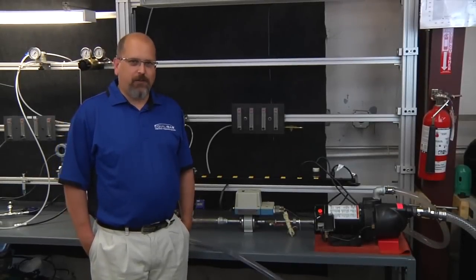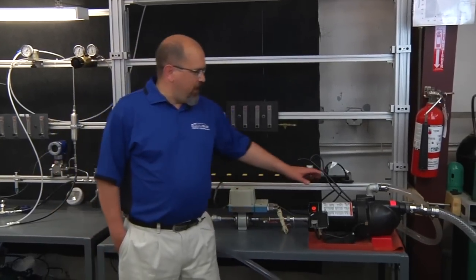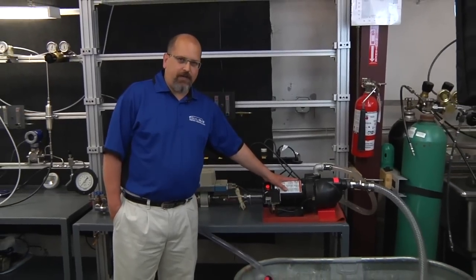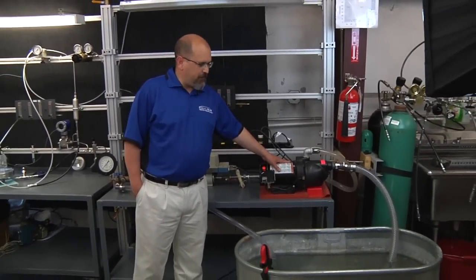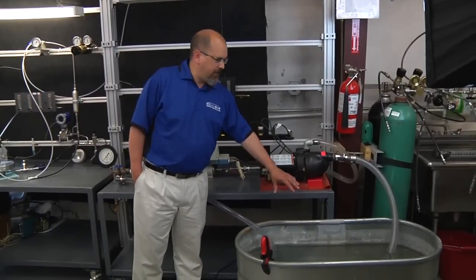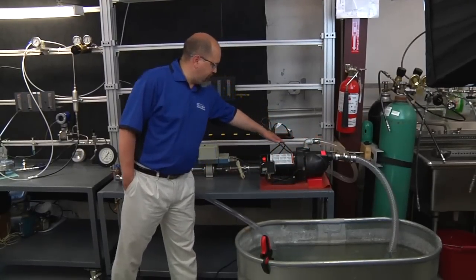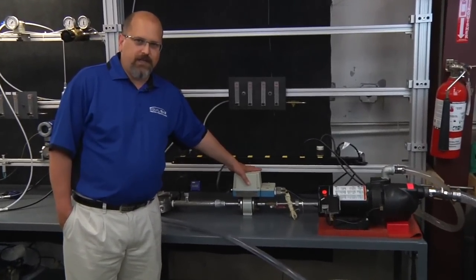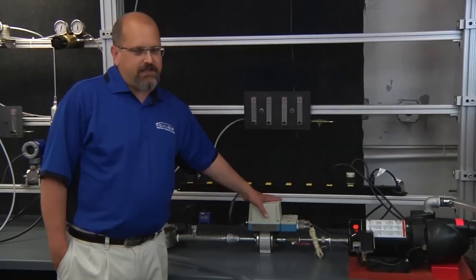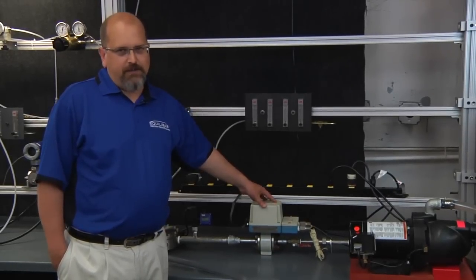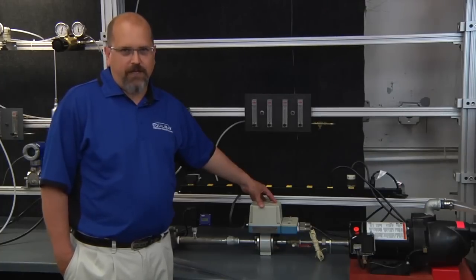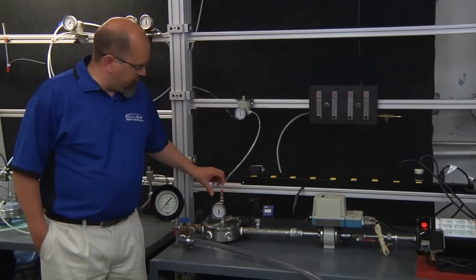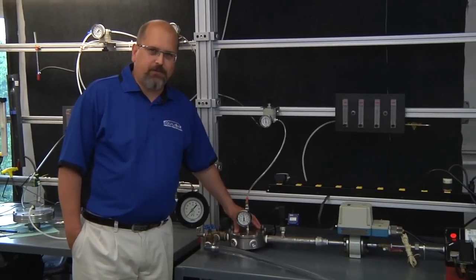We're back out in the Equilibar engineering lab. This is our non-positive displacement pump. It's a rotary impeller centrifugal type pump. It's going to be drawing fluid from this reservoir. It's going to pump the fluid at pressure through our system. Here we have a flow meter that we've borrowed from the Equilibar engineering stores, and it's not used for the control loop. It's simply here so that we can actually see and monitor what flow rate we are controlling through the pump. Out of the flow meter, we're going to come into that Equilibar precision back pressure regulator.